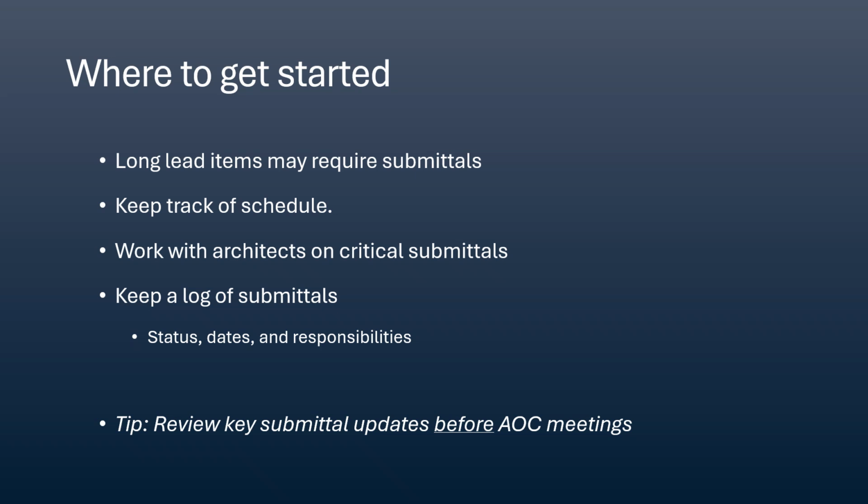And with all that said, keep track of the schedule. A really good project manager will generally understand which submittals have to happen in which order. And so they may even create a checklist or a schedule of when certain submittals are completed or when they'd like them to be completed.